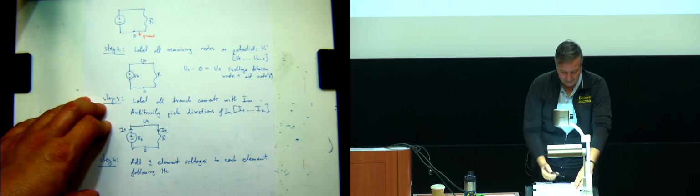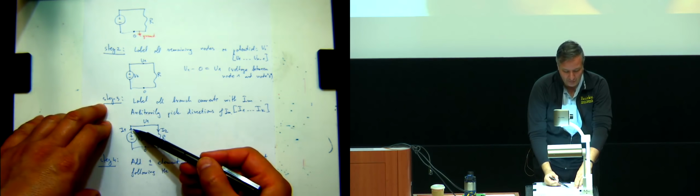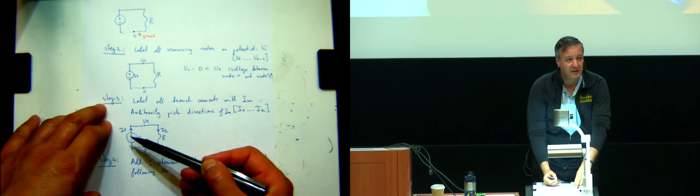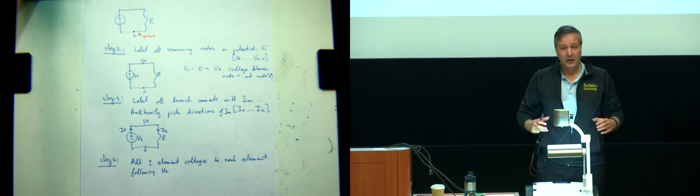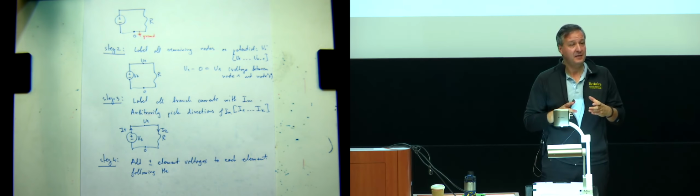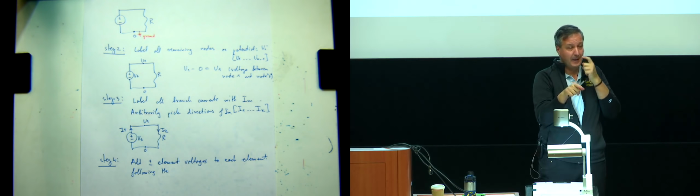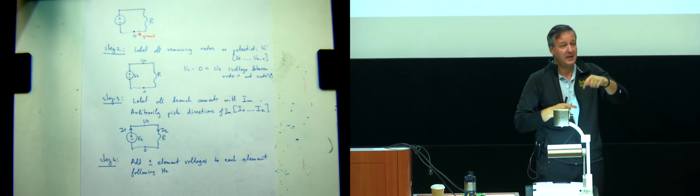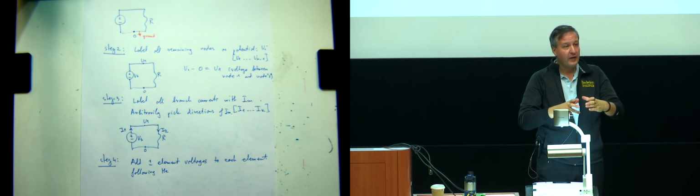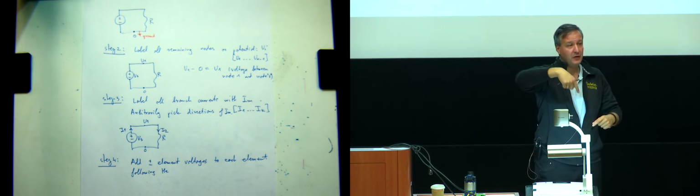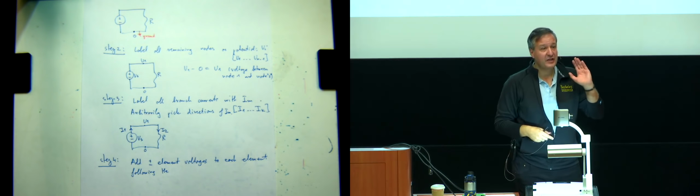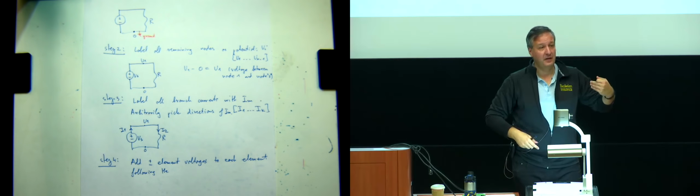The question is, is it okay if I1 is going up out of the positive of Vs? Think about it this way. I can box Vs in a little wooden box with 2 wires sticking out, and you wouldn't know where the plus inside Vs is. So for that element, I'm free to label the current any way I want, because this is just an element current that I defined.